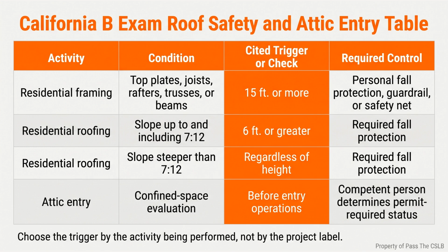Before I approve concealment, I make one final distinction. Is this roof assembly designed to breathe through intake, airspace, and exhaust, or is it designed as a compliant, unvented thermal enclosure? I do not accept a half-vented, half-sealed assembly without an approved basis.